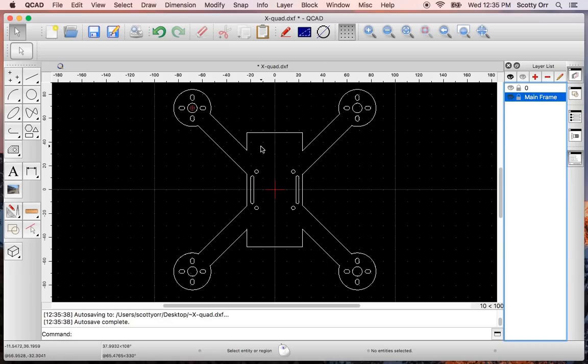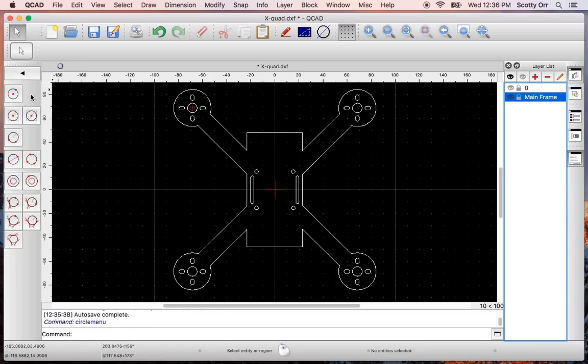And I'm going to do that anywhere where there's an angle of some sort. On the ones where the angles are pretty big, like here and here, I'm going to use a 12 millimeter diameter circle. On the sharper ones like here and like these right angles, I'm going to use a 6 millimeter diameter circle. So let me show you how to do that. And we're going to use the circle tool again.